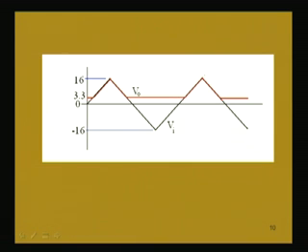So, this will be the output voltage plot that we have drawn with respect to the input voltage. In this case you see that the lower portion, when the voltage is less than 3.3 volt, is just clipped away. So, this is another example of a clipper circuit.